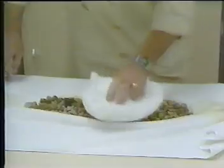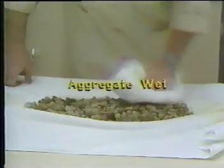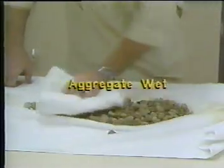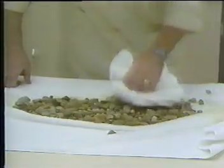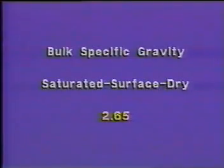Bulk specific gravity, saturated surface dry, is used if the aggregate is wet, that is, if water fills the pores of the aggregate. To calculate for bulk specific gravity, saturated surface dry, divide the weight of the saturated surface dry sample in air, 6,957 grams, by the saturated surface dry weight in air, 6,957 grams, minus the weight of the saturated test sample in water, 4,331 grams. The bulk specific gravity, saturated surface dry of our test specimen is 2.65.